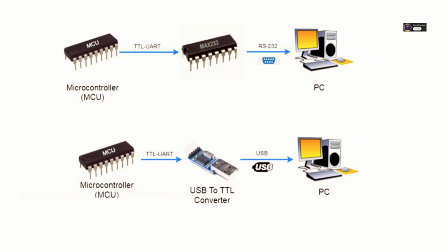Right, the dreaded magic smoke. And what about connecting, say, a 5V device to a 3.3V device? Both are TTL, but different levels. That also needs care. Connecting a 5V output directly to a 3.3V input can damage the 3.3V chip unless that specific input pin is explicitly rated as 5V tolerant.